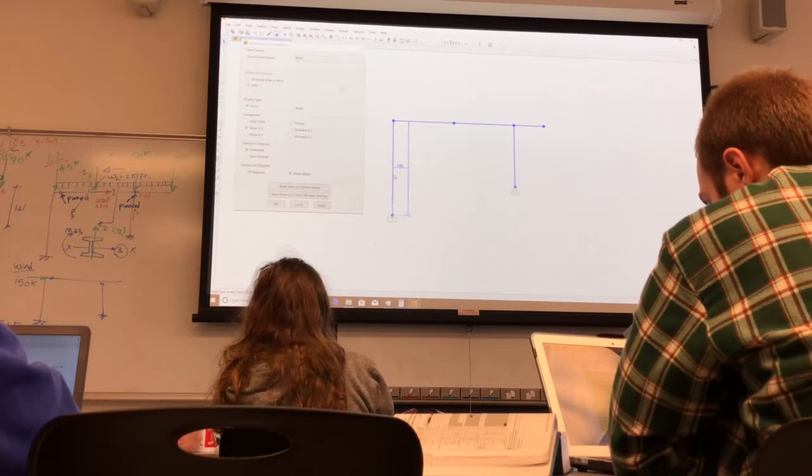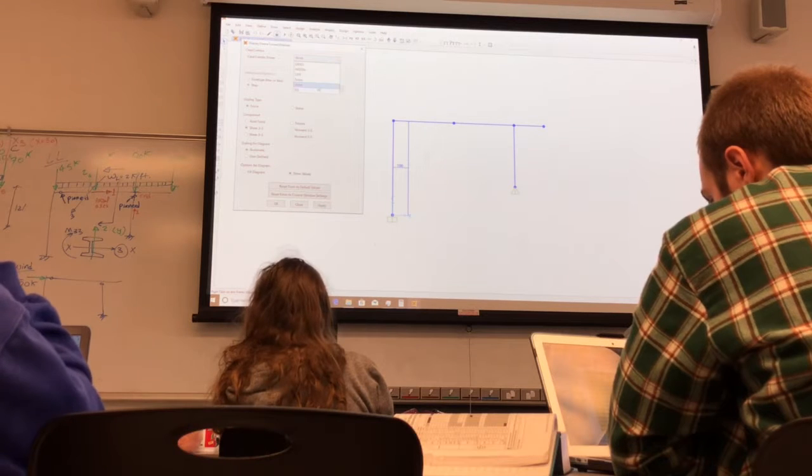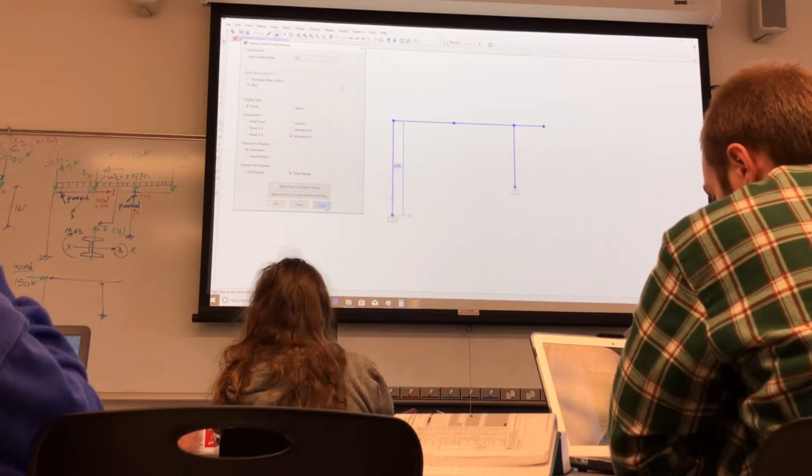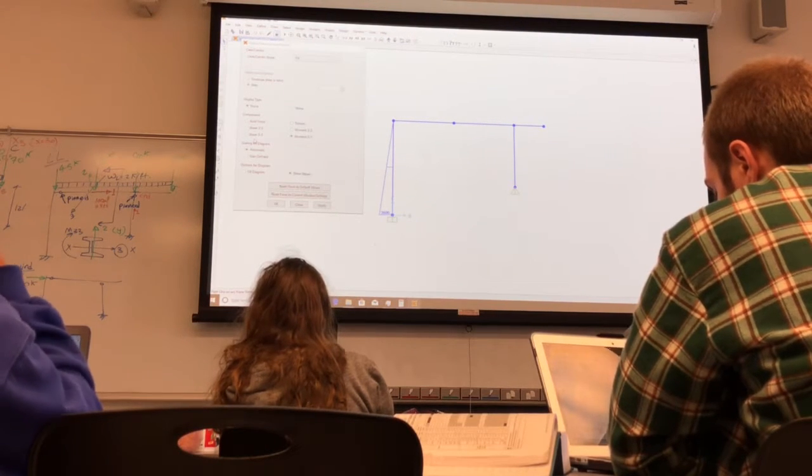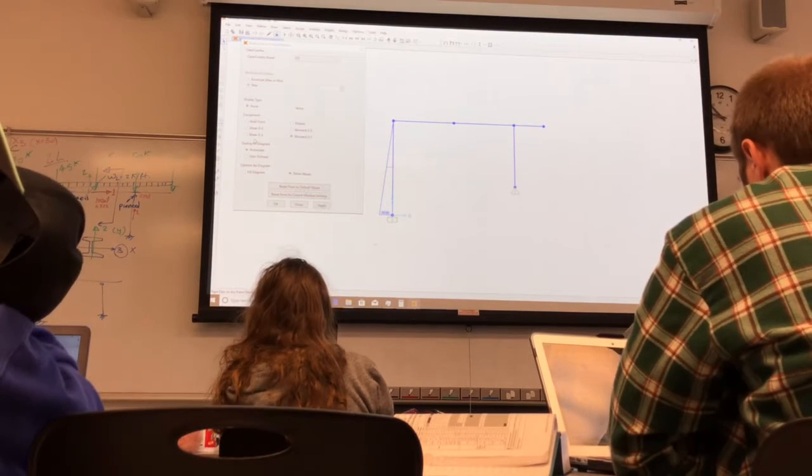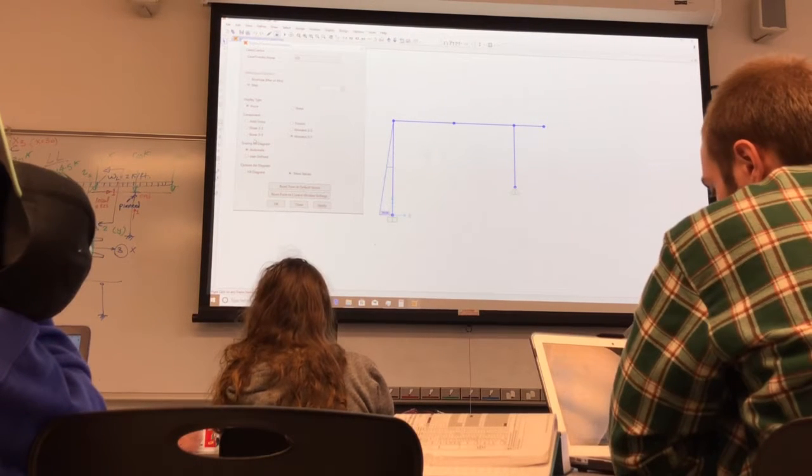So this column took all the shear force coming from wind, the 150. Same with the earthquake. You'll see this column is taking care of the whole thing. And that's how the moment diagram looks for the other loads. So that's just doing structural analysis. We haven't done anything new so far. That's analysis, structures 1.